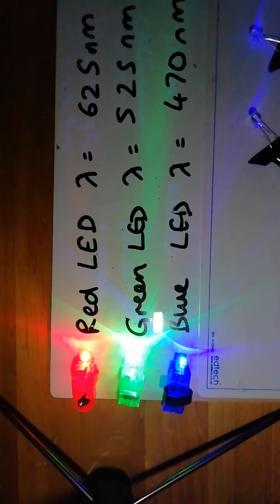When a photon is absorbed, it creates an electron and a hole. And the way that the semiconductor is designed, the electrons tend to be pushed away from that junction into the N-type silicon, making it more negative, and the holes tend to be pushed into the positively charged P-type silicon and make it more positive. So we create an imbalance in the charges.